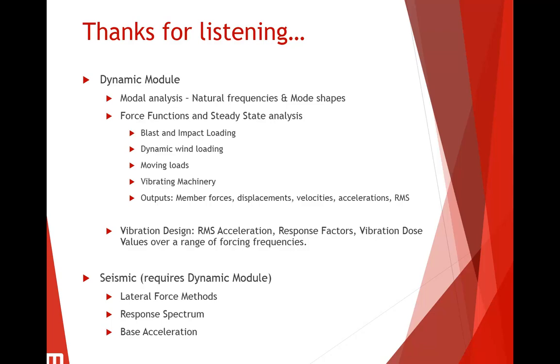So you could use this for blast and impact loading, dynamic wind loading, like with the Tacoma Narrows Bridge, and moving loads and vibrating machinery, as I showed you before. And with all of these, you can have your node watch set up, see how the node's moving over time, but more importantly, you can output the member forces in your structure at any given time during this analysis back to MasterFrame and use it in MasterBeam to design your members and design them so that they account for these extra dynamic loads that would otherwise possibly get overlooked.